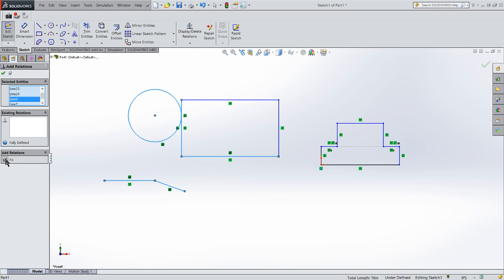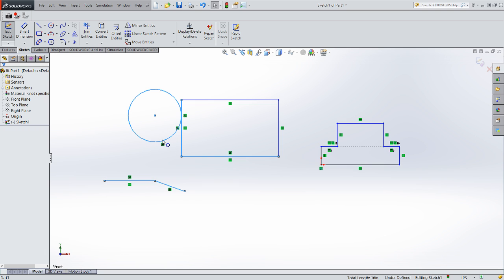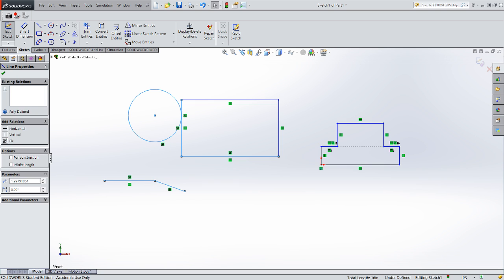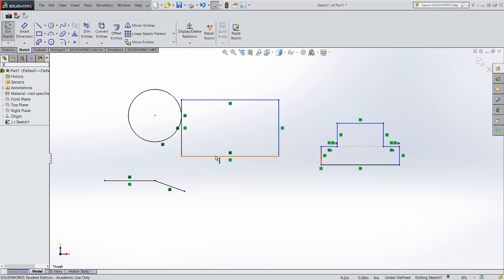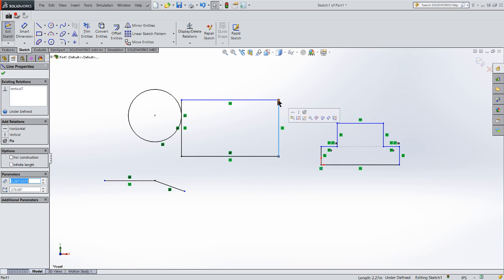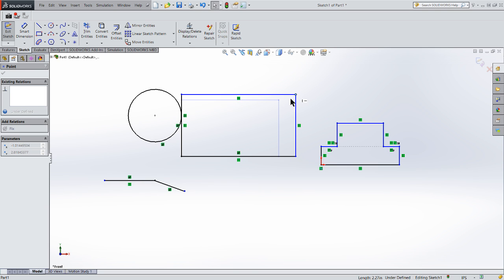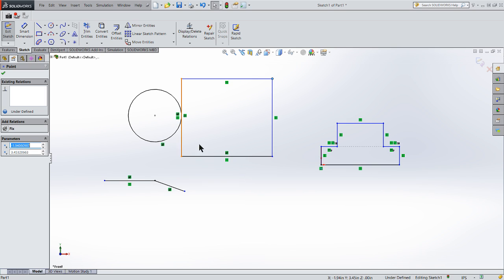And we have this fix. Fix is essentially exactly what it looks like, an anchor. So I'll click on OK. Once I put that anchor in, it's not moving. It's just like attaching it coincident to the origin. It doesn't move. Now the lines that I did not fix, those will move, but the lines that I fixed turn black and won't move. All right, that's an introduction to geometric constraints.